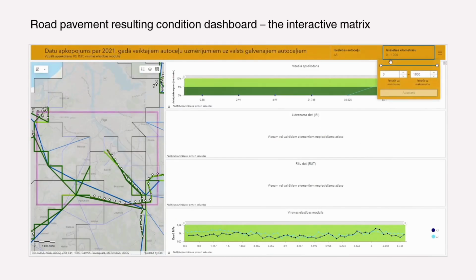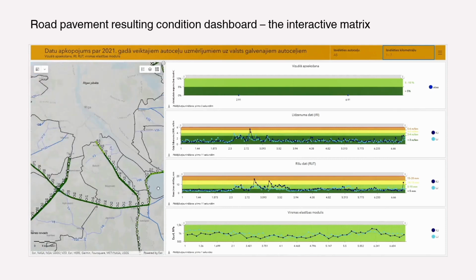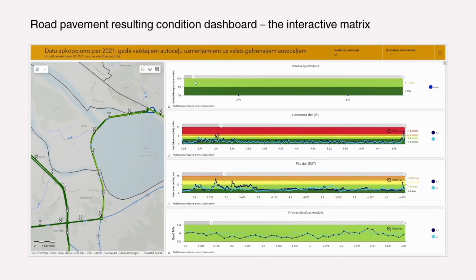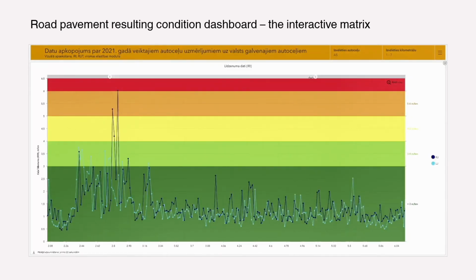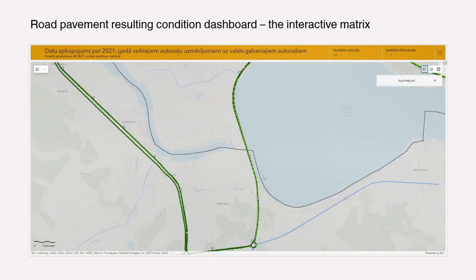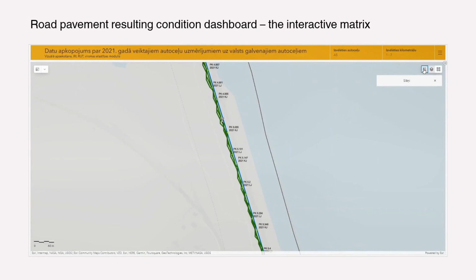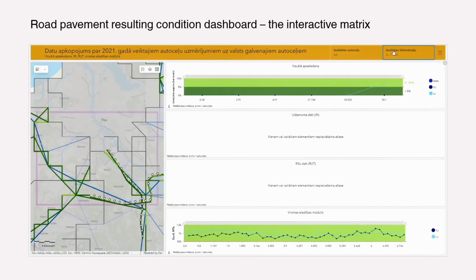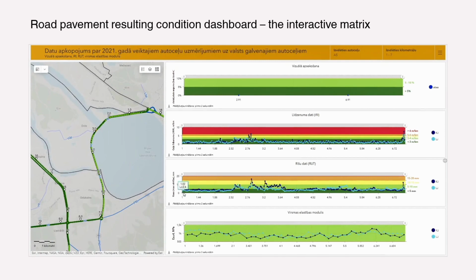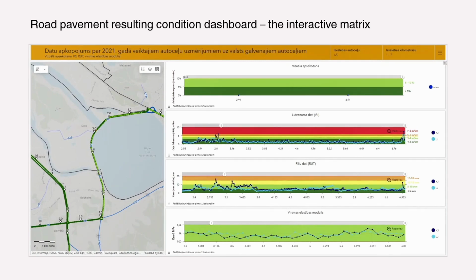And for the joint analysis of measurements, this main dashboard is created where datasets are analyzed in 4 single-line graphs. Each graph is visualized with a linked single linear reference, and in the background has this colorized A to F assessment that allows the resulting pavement condition of a road section to be determined, and consequently deduce whether a section of road can be resurfaced, and then select the appropriate type of resurfacing design from these guidelines.